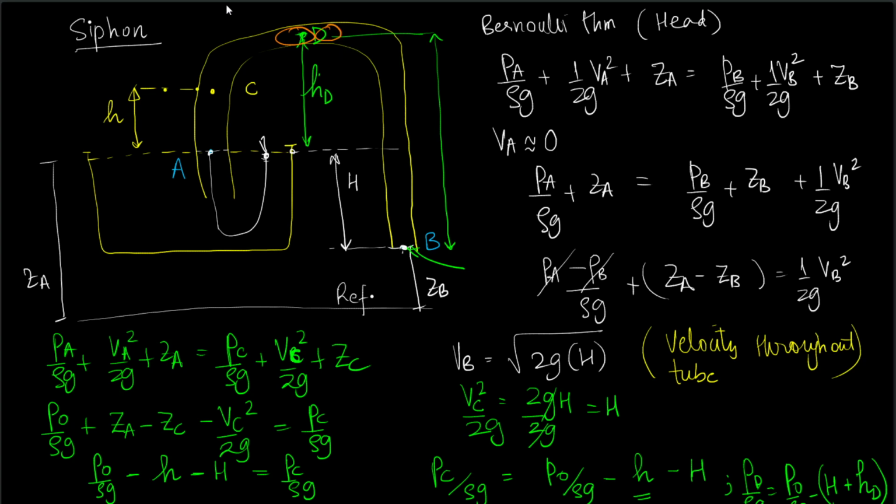Now, air or vapor is quite compressible, so during the flow, it can prevent the flow by merely allowing for compression of the air bubble. So allowing for a compression in the air bubble leads to a blocking of the flow. It will appear as if everything has stopped, but in reality, a vapor bubble has formed.